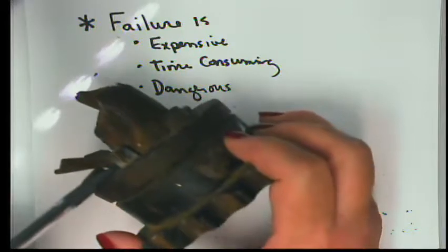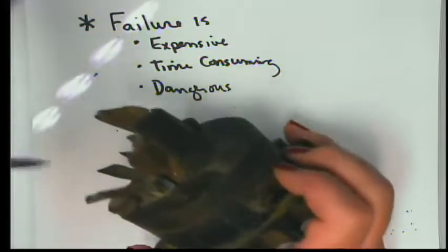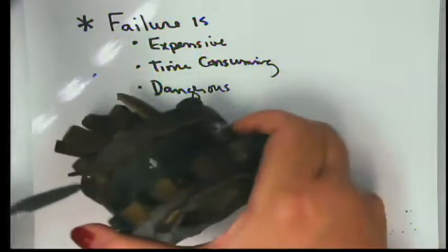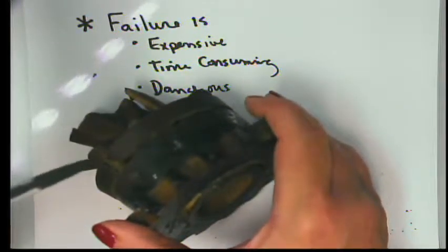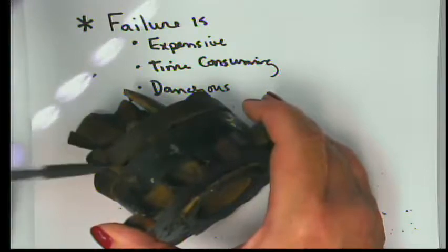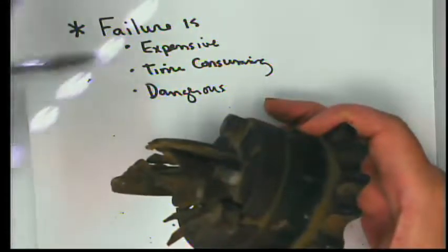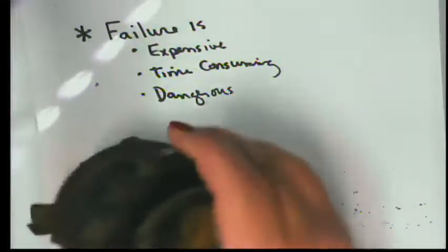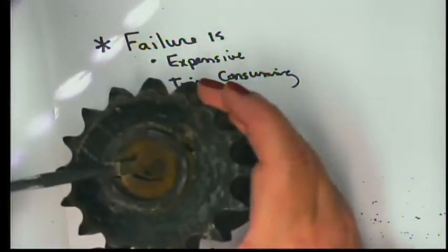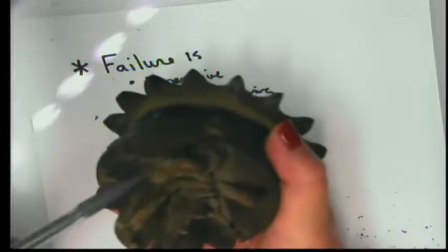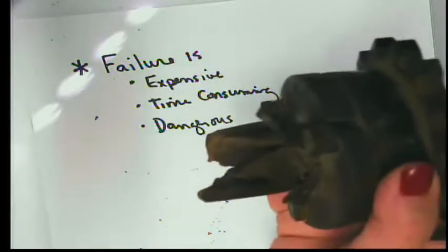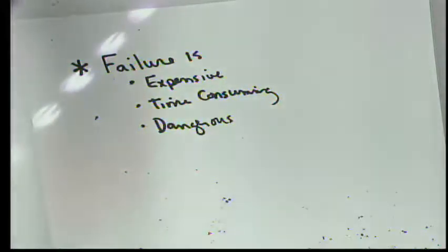And it blew up, right? So the key is intact, right? This is a problem. Everything else is destroyed. You can see that this place where the bolt goes into it, there's a rupture here. All of this entire shaft twisted off, and yet you can see the key down below, and the key up above is just fine. So this is not a good failure. This is not the way you want it to fail.